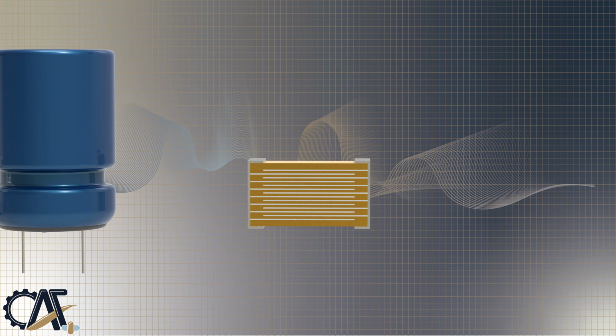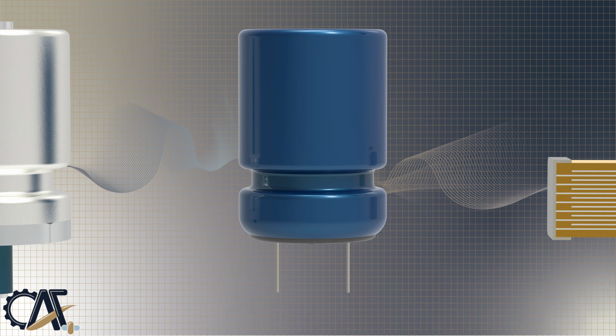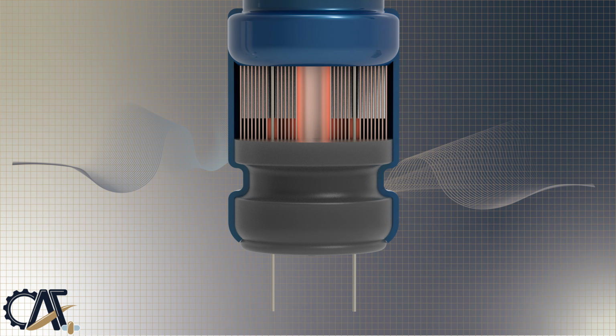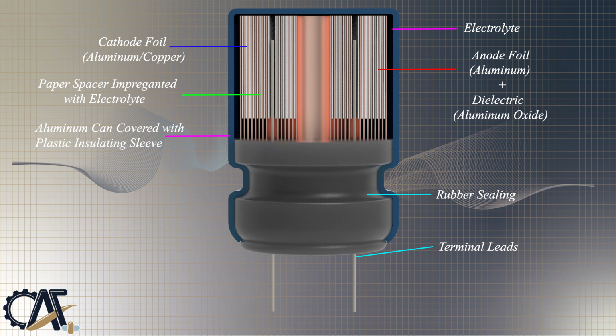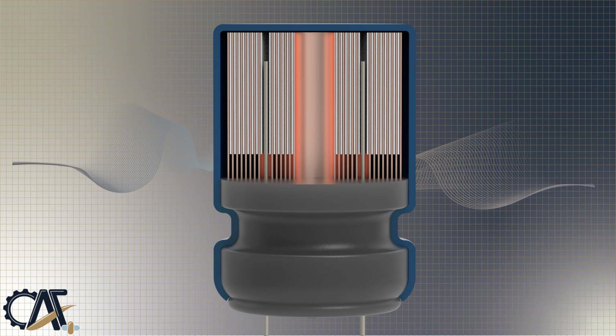The next example is an electrolytic capacitor. They are popularly known as polarized capacitors, wherein the anode has a more positive voltage than the cathode. The electrolytic capacitor construction involves two thin layers of aluminum or copper foil, the plain foil and the etched foil. These two foils are separated by a paper spacer impregnated with electrolyte. The electrolyte can be in the form of solid, liquid or gel.